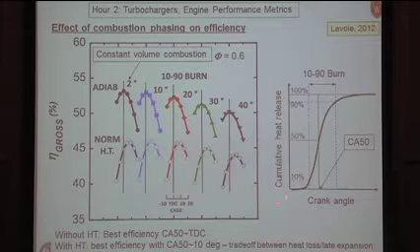So here's the cumulative heat release that goes from 0 before combustion to whatever the final heat release was. The 50% burn point is called CA50. That's this crank angle here. The 10% burn point is here. You just burn 10% of the fuel. Here's the 90%. So the CA50 is indicated. The CA10 to 90 is the time between these two dotted lines here. So what they did in the analysis was first they assumed that the engine was adiabatic, so no heat transfer losses.